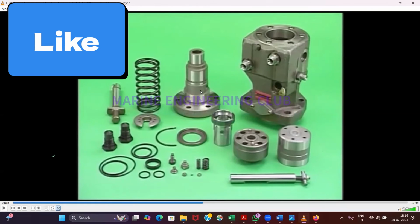This is your barrel, and this is the plunger. Now, plunger and barrel cannot be interchanged. It cannot be that you put this plunger in some other barrel. No, it comes as a single part. Even in spare parts, both will come together, for main engine and for auxiliary engine. It has to be changed together. Is it clear? Yes.